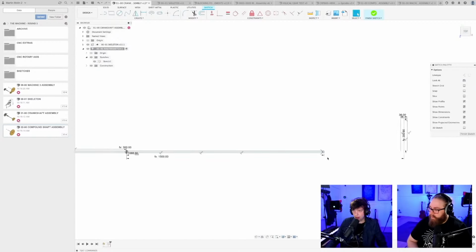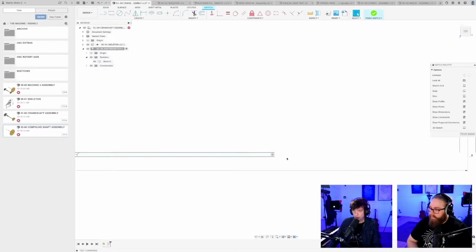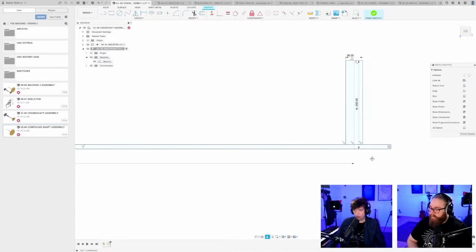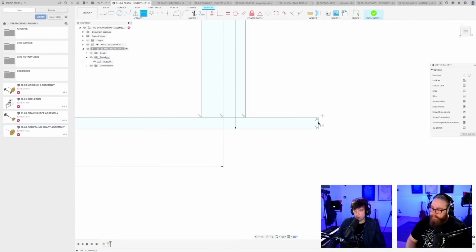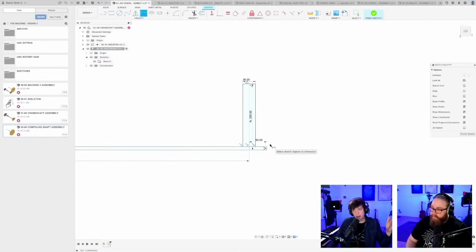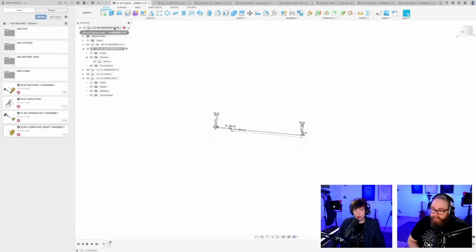You make this length, hang on. So remove this. So you make the length of the shaft dependent on the parameter position. So instead I say, hang on a minute, you are 5 centimeters outside the gear at all times. So by adding the distance here instead to the middle of the design, the shaft will always change when I change the parameter of the gear position. So let's try this again. Now I think the timeline is fixed.